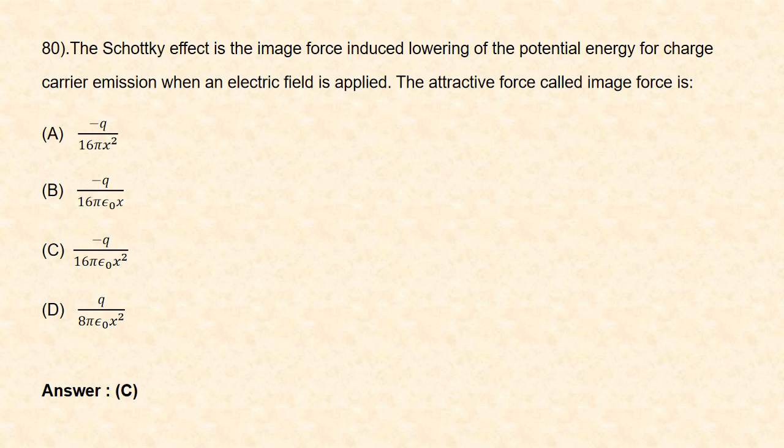And the next question, the Schottky effect is the image force induced lowering of the potential energy for charge carrier emission when an electric field is applied. Here the attractive force, called image force, is given by the formula −q²/(16π ε₀ x²). So option C is the correct answer.